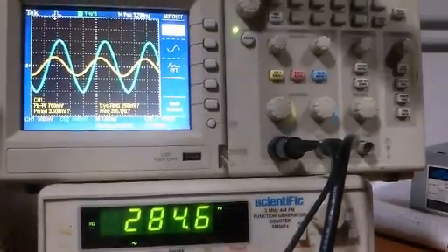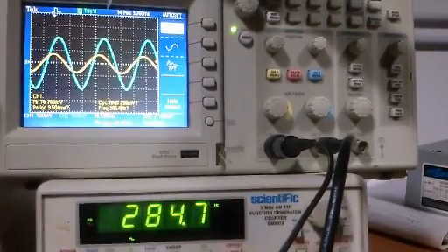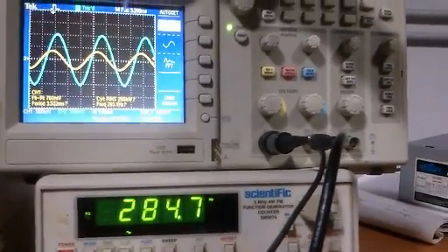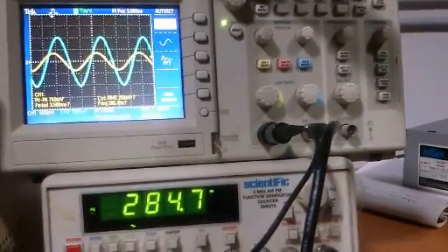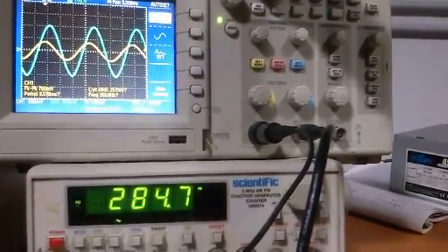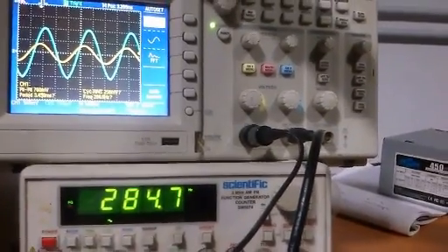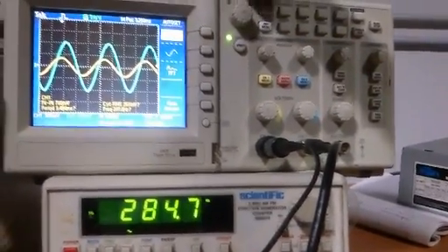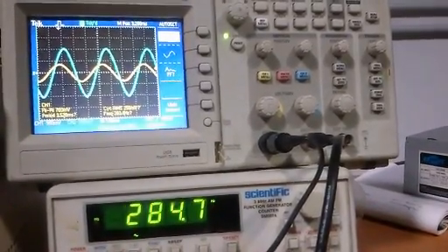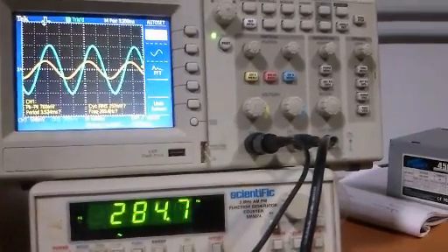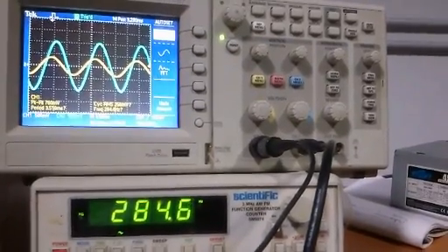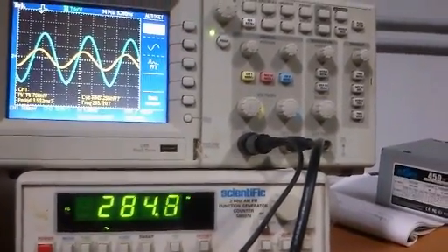and so now the phase difference is even less than 90 degrees, and as the frequency of operation of the filter goes higher and higher, the phase difference goes to 0. This can be obtained from the transfer function, and so the phase changes from 180 degrees to 0, and the magnitude changes from 0 dB to minus infinity. 0 dB corresponds to a magnitude response of 1, and minus infinity corresponds to a magnitude response of 0. So at infinity, when the frequency is very high, essentially the signal is totally attenuated.